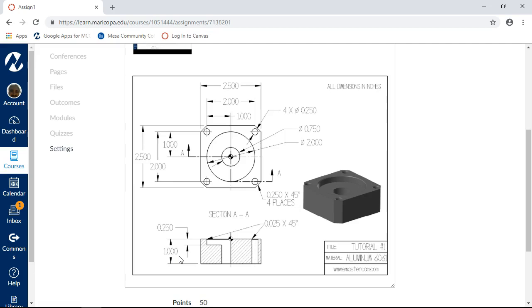My recommendation is to always start at medium to low feeds and speeds. When you get it out to the machine and you can observe and react to the cutting conditions, then you can make it go a little faster. Then you can get them a little more aggressive. Get the parts being made and turned over to your operator, to your setup, and then come back and start to fine tune and resolve issues as they occur.